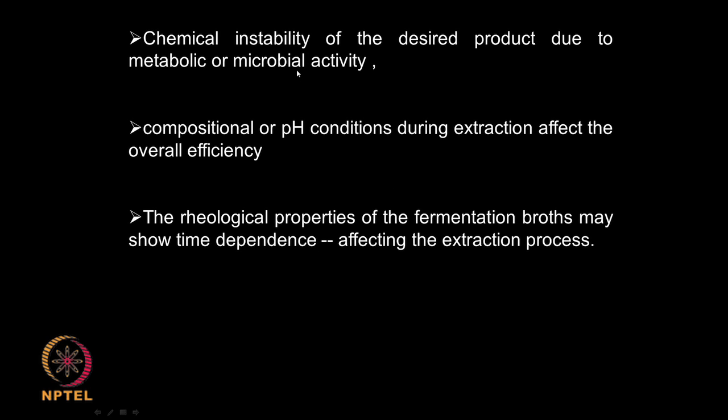There could be chemical instabilities, because the desired product may be unstable because of some microbial activity or metabolic activity, that means some metabolites are present which may be degrading your product. Composition or pH conditions during extraction may affect the overall efficiency. Rheological property, the viscosity: fermentation broths are highly viscous, and when you are using a solvent and trying to extract, it is going to be a big problem, because viscosity will definitely affect the mass transfer as well as